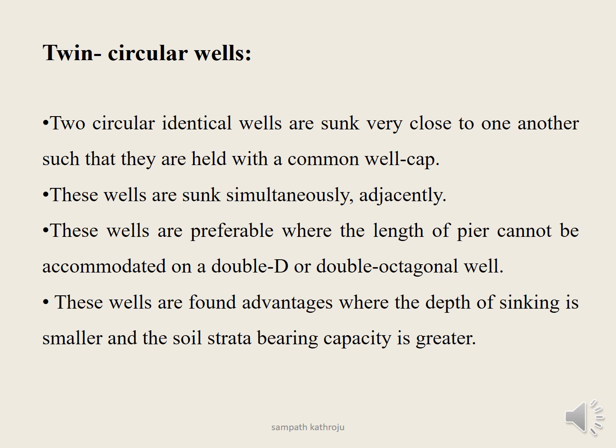Twin circular wells. These are close to one another. They are also used where the area is large and cannot be accommodated in double D or double octagonal well, and are advantageous where the depth of sinking is smaller and the soil strata bearing capacity is greater.